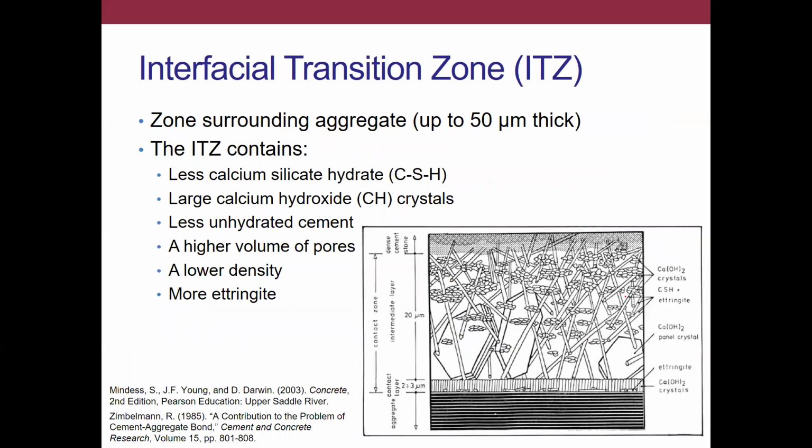So this then led to the primary investigation that I'll be talking about here, and that is looking at the interfacial transition zone. All right, so in all concrete materials, the aggregates are surrounded by what's known as the ITZ, the interfacial transition zone, and it's essentially due to the wall effect. All right, so your cement particles have a finite gradation.